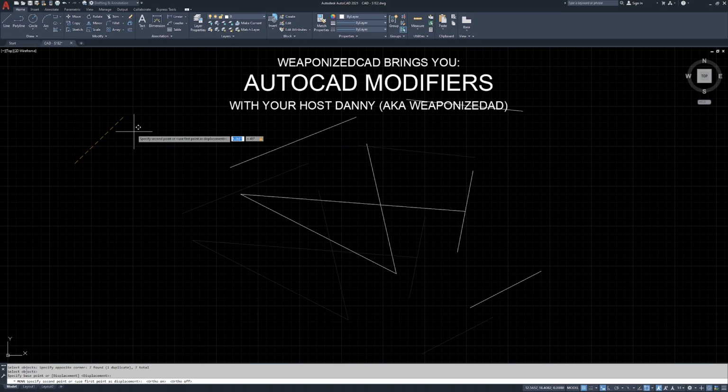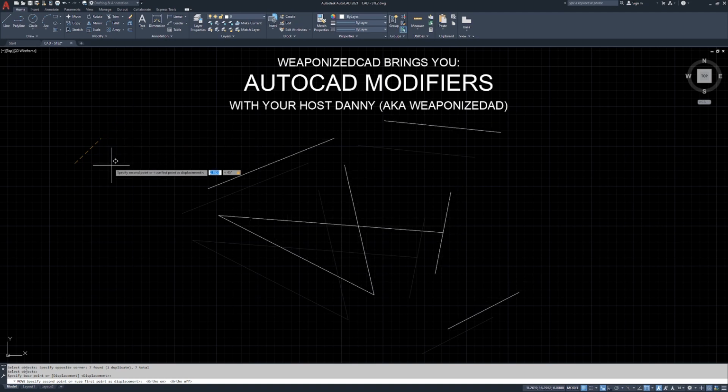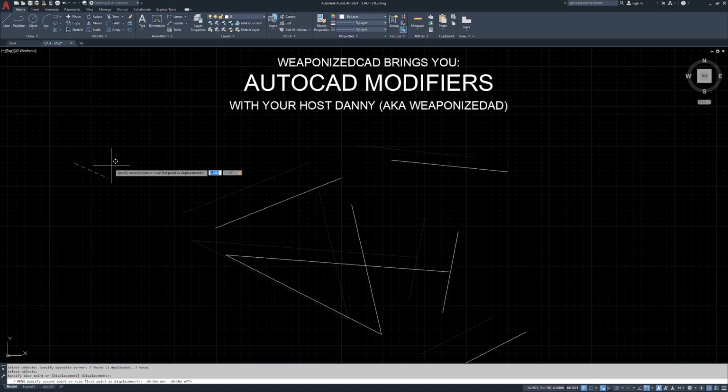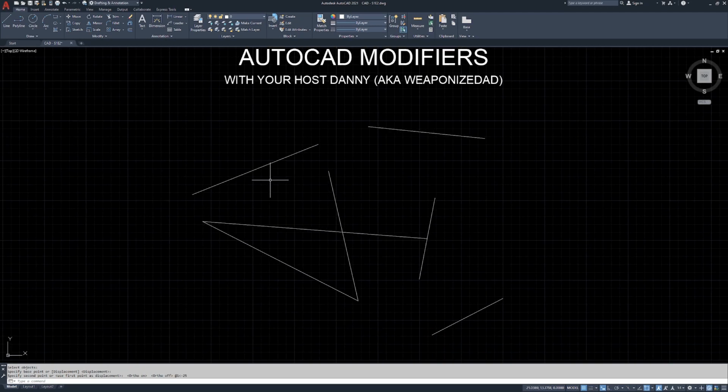So let's just move it 1, because otherwise it's going to go into my lines up there. So we locked the 45 degrees, and this isn't locked in a sense that you can't change it if you decide, I don't really need 45 degrees. Let's say I wanted 25 degrees. Or let's say I wanted negative 25 degrees. And then we move it 1, and we hit enter. And what it did was it moved these lines 25 degrees southeast 1 unit. So that's pretty much the move command.